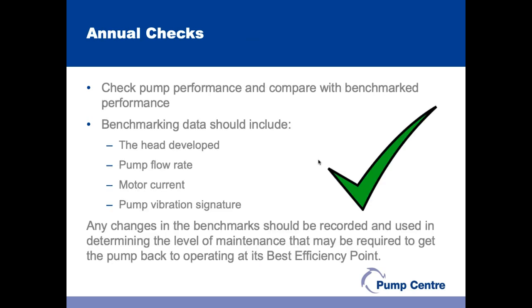And on an annual basis, one of the maintenance checks that's really useful is to carry out a comparison between the current performance of a pump and the benchmarked performance. In other words, the performance that pump was exhibiting when it was first commissioned.